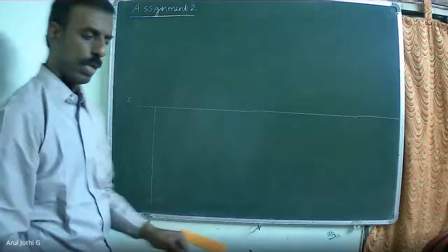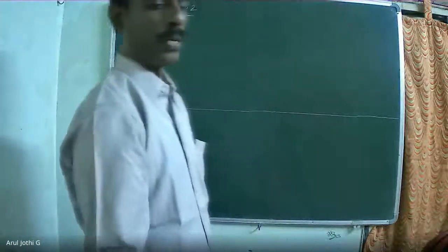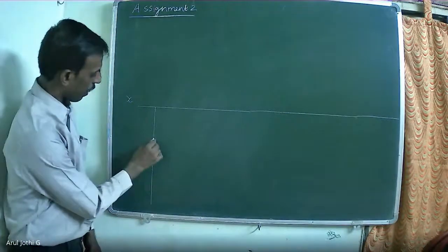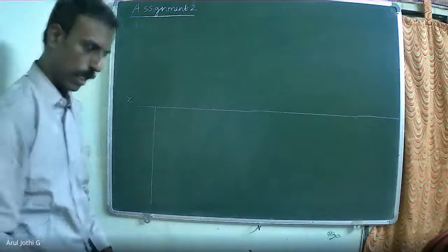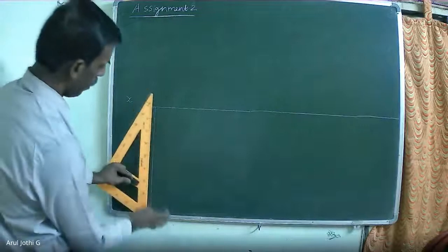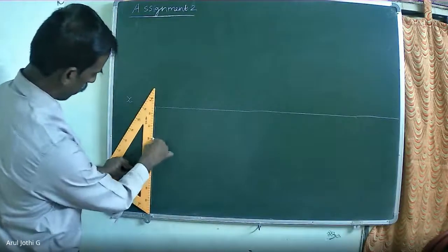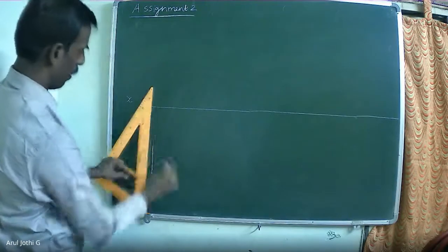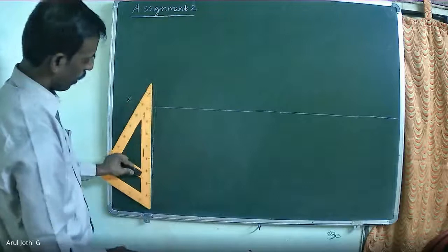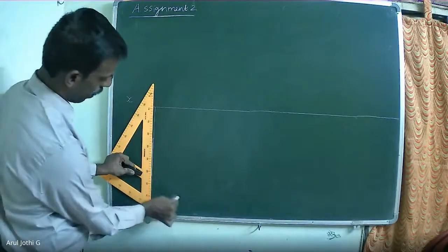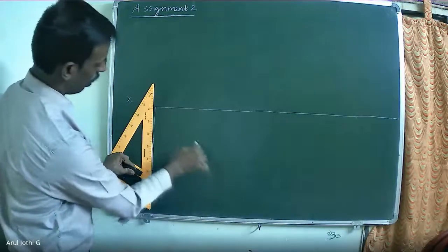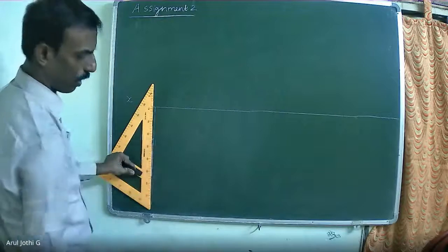On this line, you have to keep the side of the template. Now I am going to use the protractor and mark 30 mm side. Using the scale, you mark 30 mm. When I draw the pentagon, in the template you will have 5 corner points: 1, 2, 3, 4, 5. You can draw the pentagon.